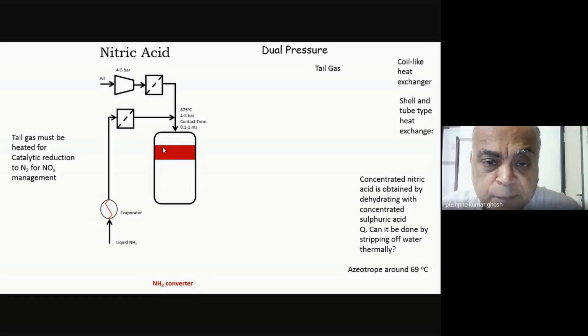The alloy is more stable, and it also gave a higher conversion, presumably because there were no losses of platinum, so that also may have helped in improving the conversion. Because it is coming in at a high temperature, as we discussed, and the high temperature was required, really, one because we want a very high speed of reaction. The rate of reaction has got to be very high. The second, we had introduced pressure just so that the residence time in the catalyst bed is minimal, and you can see it is typically from 0.1 to 1 millisecond.